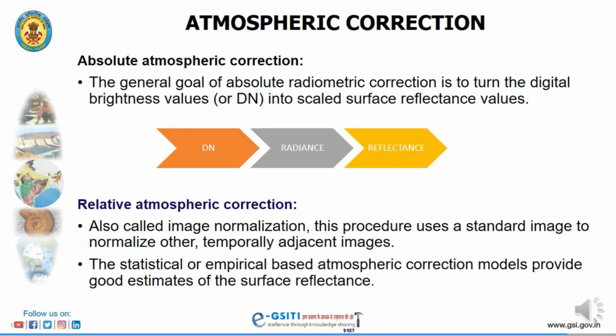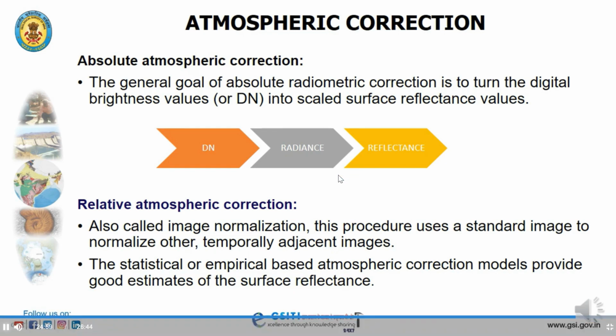Other sources of errors are due to the varying illumination geometry, dependent on the sun azimuth and elevation angle with ground terrain. This will generate a radiometric error in our data. So we are performing various atmospheric corrections on our data.